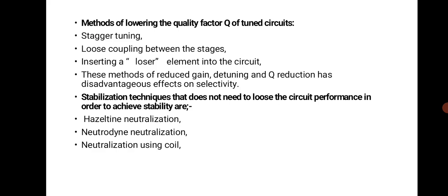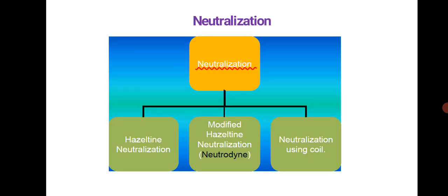So we go for certain stabilization techniques which will not lose the circuit performance. In order to achieve stability, we use Hazeltine neutralization, Neutrodyne neutralization, neutralization using coil, and still we have one more, which is Rice neutralization.